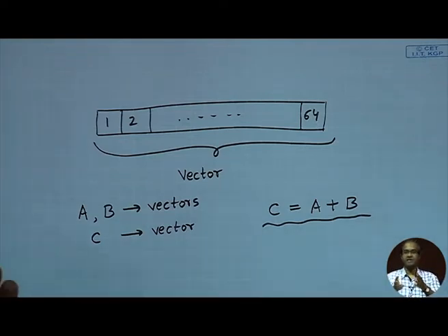So, in a conventional processor where this kind of vector operation is not there, we had to use a loop. In every iteration, you have to add one pair of numbers, then decrement a loop counter, check for 0 or some condition, then branch back. So there you see some loop overheads, decrementing a counter, branching, but here it is a single instruction, there are no loop overheads. So expectedly this should run faster.